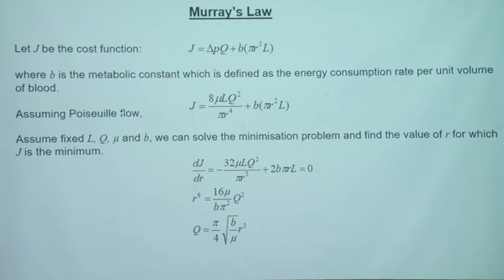Now, we consider the flow to be steady, which is a big assumption. Consider steady, unidirectional flow, using all the assumptions that we've stated earlier, then the pressure gradient can be expressed as a function of the flow rate, and so this pumping power can be reduced into this form. I think anyone who took first year engineering fluid mechanics will know that, when you solve flow through a pipe, you do this as well. So here is an expression, replacing delta P with the expression involving the viscosity of the fluid, the volumetric flow rate, the length of the pipe, and the radius of the pipe.